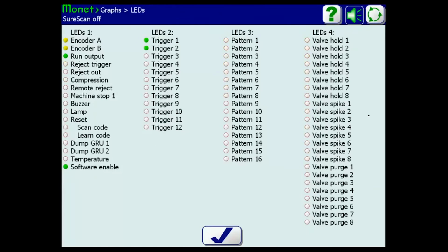On your application, your hot melt applicators, your hot melt valves, do not require a spike duration. Our standard spike voltage signal is 48 volts, which you do not use. It's a duration value in milliseconds, and we set that to 0 milliseconds for your hot melt applicators because they do not require a spike voltage.